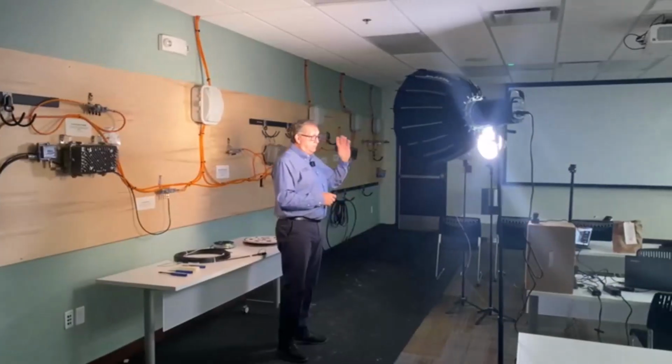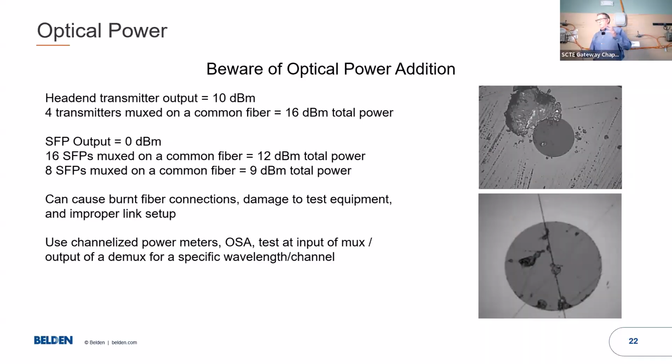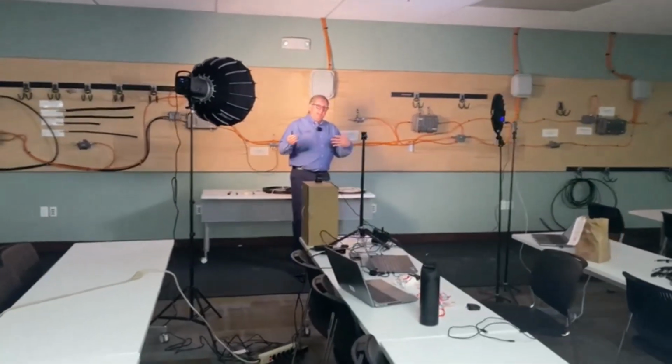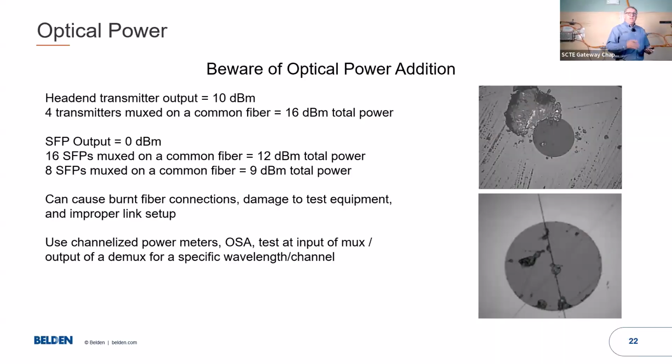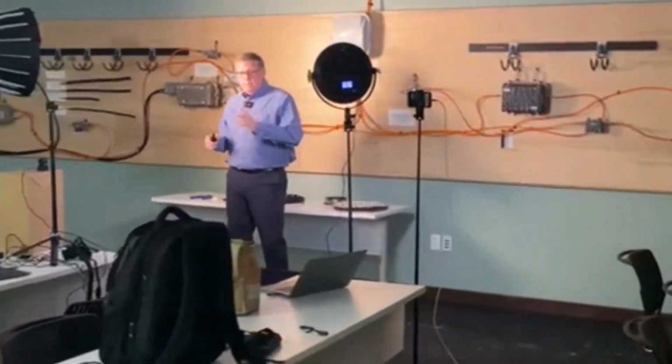I got +6. Well, we put a 6 dB pad in the head end. A few years later, tools improve, and we're working on optimizing the head ends, optimizing the nodes, the fields, because you can see the signal to noise, the MERs were below the spec that they wanted. So we went through and we optimized the links.